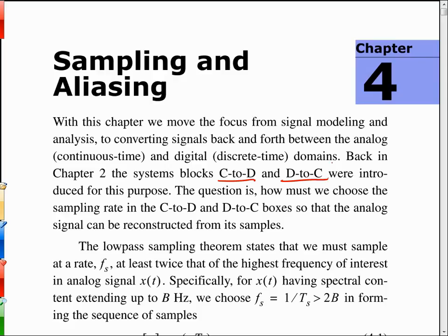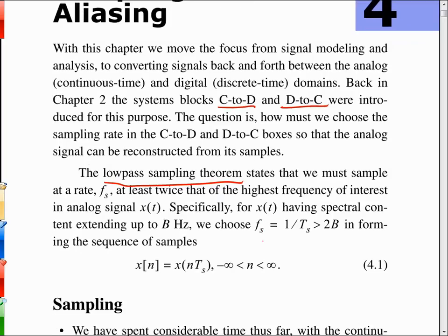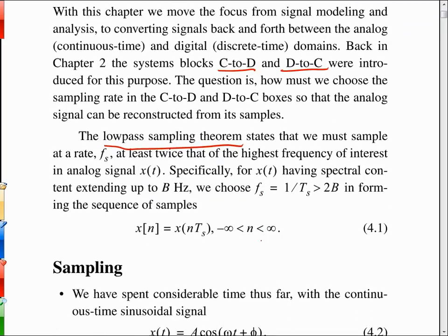And then this chapter also, of course, has the sampling theory, and the low-pass sampling theorem is one of the fundamental results that comes out of here, how that works and how we go from continuous to discrete and then back again, actually proving that and letting you see how that works. Most everybody believes in it because that's how you listen to digital audio when you listen to your music player. It's come from a digital format back to the analog domain, but what are some of the particulars of that?